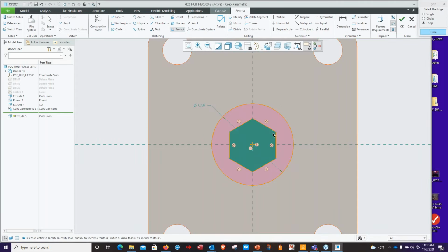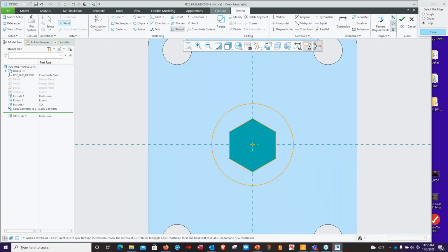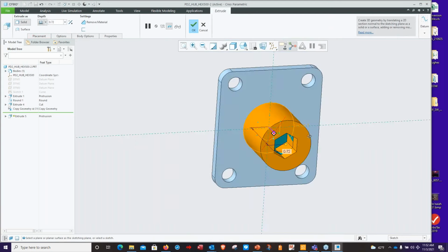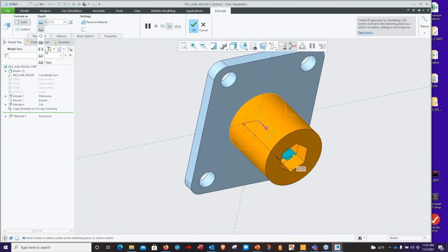And depending on how you want that dimensioned, whatever your design intent is, or if it's going to be for the drawing, there are a couple different options we can do. In this case, we want to perhaps make sure that there's a minimum distance of steel or plastic, whatever this component is made of, 0.18. You know, if we want, we can always put a dimension, a diameter, a radius, whatever is your company's policy. Select OK. So it just picks a random depth.